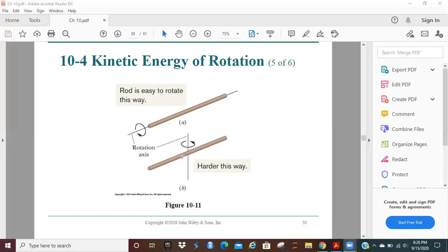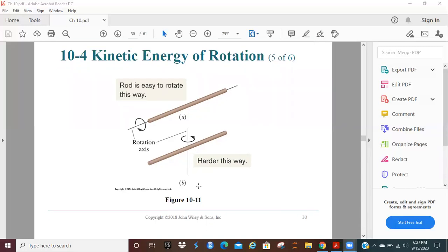Once the mass, even if this is uniform, the mass really doesn't change. But once you start multiplying it by the radius, and once that radius starts to get pretty far out, then the moment of inertia really starts to resist that change. So the mass has an effect, but that square on the radius is really going to start to govern pretty strongly over the mass term.